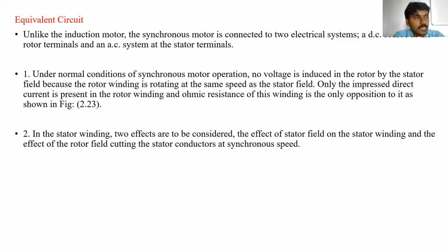We are not giving any supply to the rotor circuit, so the EMF is induced in the rotor circuit by the stator supply. But in the synchronous motor, under normal operating conditions, no voltage is induced in the rotor by the stator field.